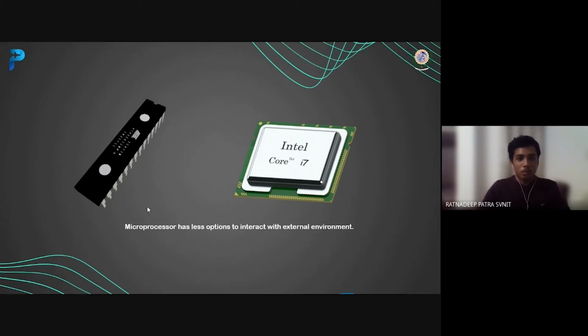So we just have to connect ADC elements or DACs to the microprocessor. We have to connect those things externally. And as we are connecting these things externally, there are more electronic components present in the whole system, so the microprocessor is consuming more power compared to a microcontroller.